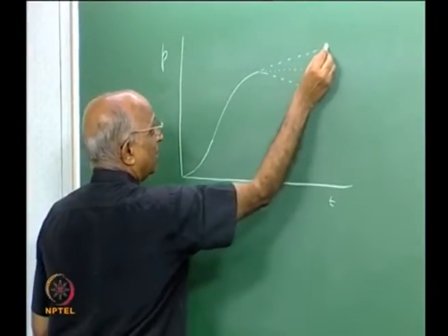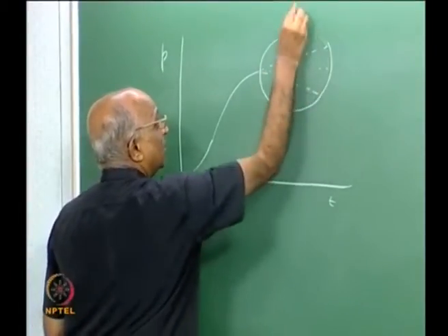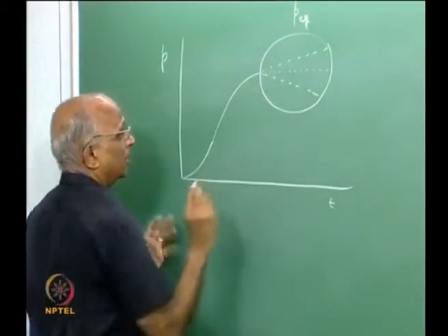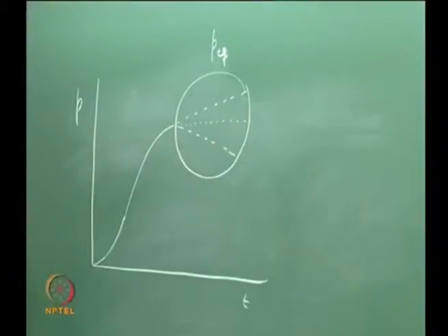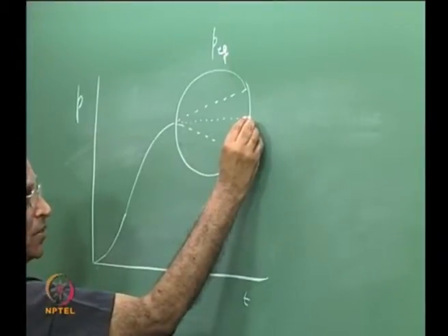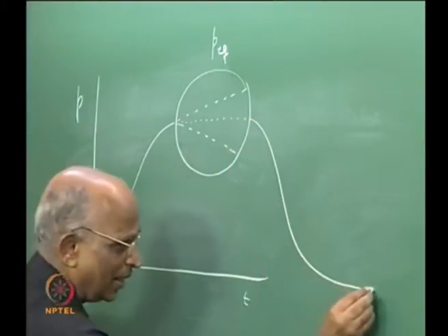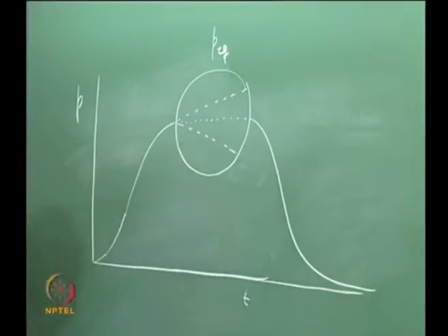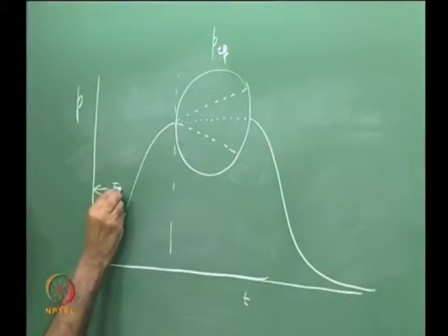Mind you, this particular zone is equilibrium pressure, that means a steady state pressure. At the end of this, all the propellant gets consumed, it goes like this and comes back over here. This is the transient for ignition, the ignition transient.